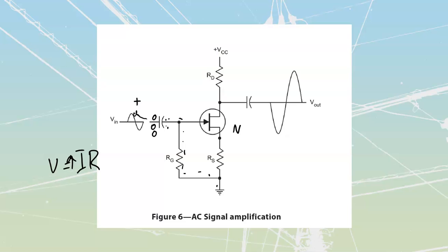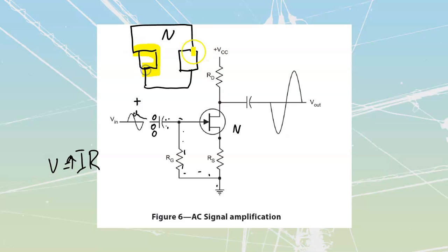And if I were to draw this thing, let's just actually do that. Yeah, draw like that. It's my N type of channel that I'm going to have. We've got our two little P-type blocks that are going to be in right over here. And we've got that depletion region that's going to be just around the outside of these. Okay? So I've got all of that laid out here right now, and then we said that we increased the value of positive voltage that we had applied to this section over here, which is going to be my P-type of material.